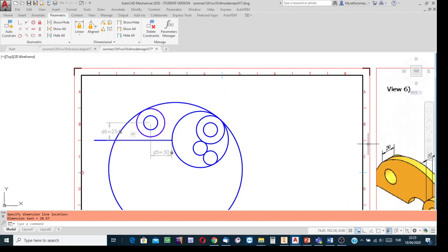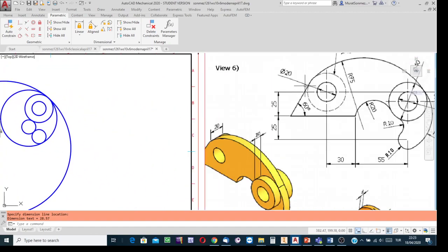And then, remember, in applying the classical method for having such a line, it has only one tangent point. There are 4 tricks. Change snap configuration, trick 1. Have the at symbol, trick 2. And then click on the angle tab. It is the key. In the structure of the keyboard, the less than and greater than symbols are the third trick.